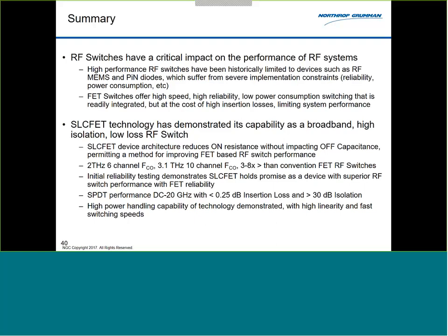You go ahead and do the math, and it's a very small capacitance associated with the switching energy. So 6 watts is passing through the device, but you're not switching that. That's not the energy that you're switching back and forth. That's the RF energy going through. The charge you're moving with an RF device is just the charge in the channel that you're pushing back and forth, which isn't 6 watts. That's very, very tiny. The 6 watts is just the CW. I'm allowing 6 watts to pass through or not, as a gatekeeper.